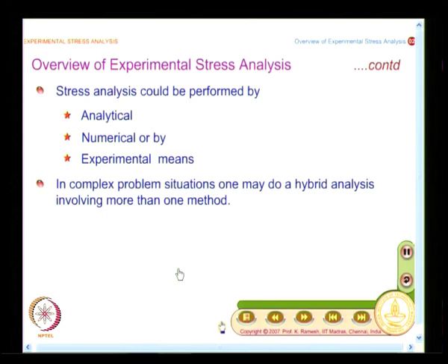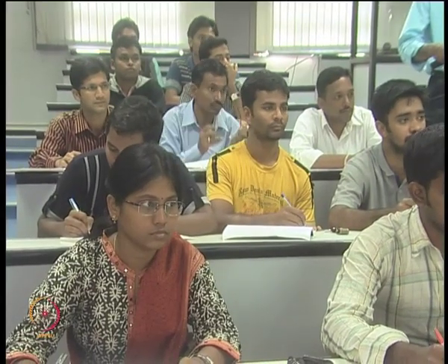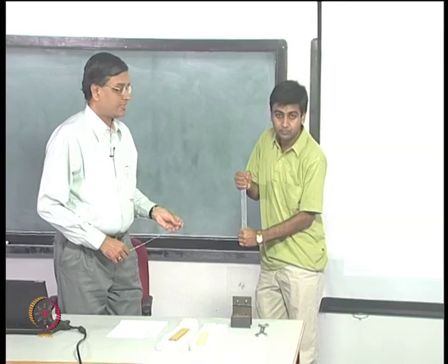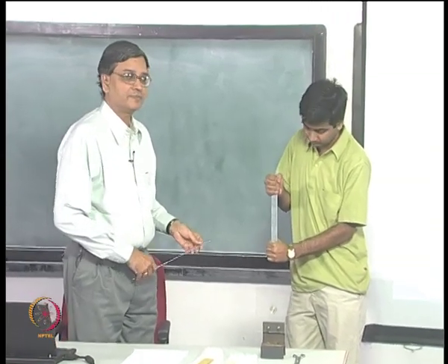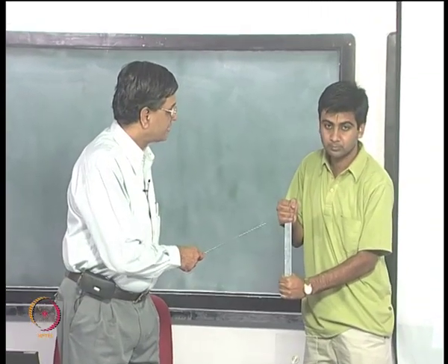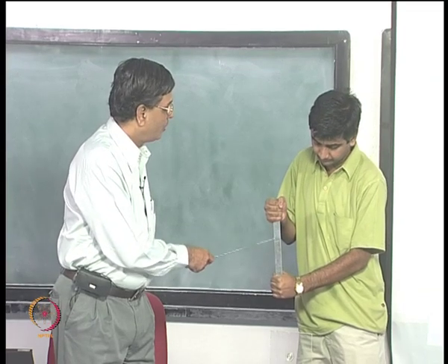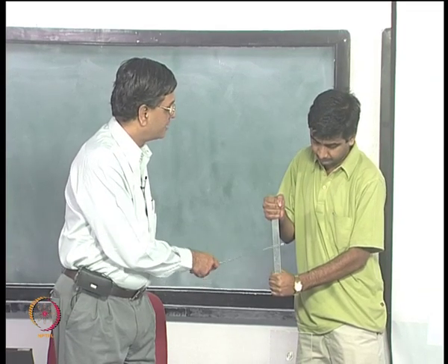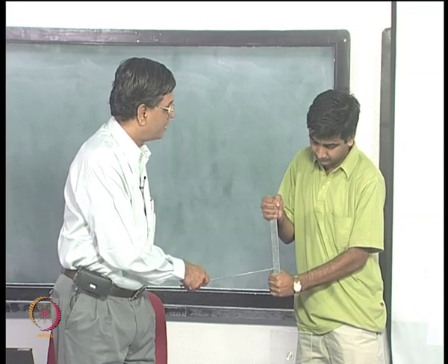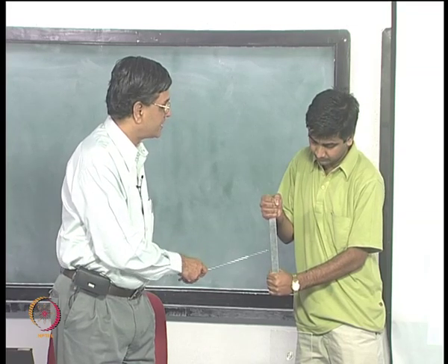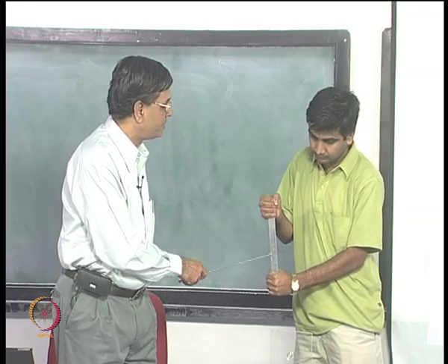And if you get into analytical methods, what we find is you get a conceptual understanding on the nature of stress fields. For example, can I have one of the students come here and then show this model? And one of the simplest problems that is first taken in a course in strength of materials is a slender bar pulled in tension, and in this zone away from the grips, you all know that stress is constant and that is given by P by A.